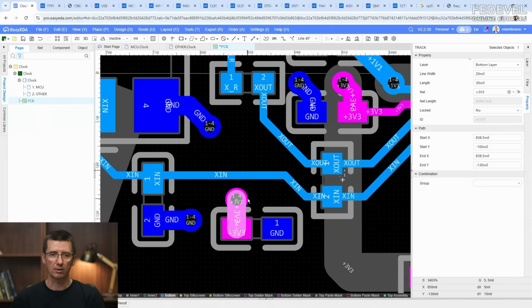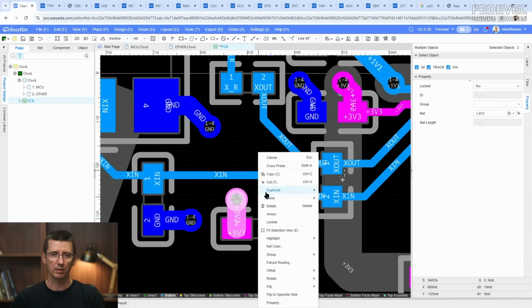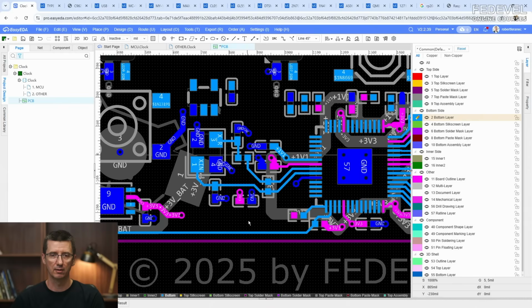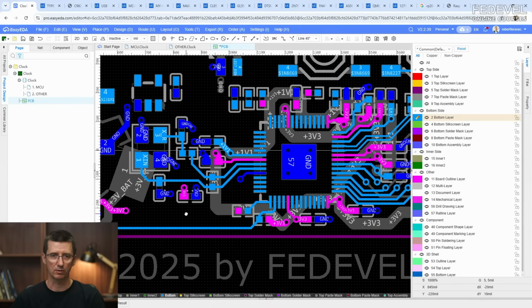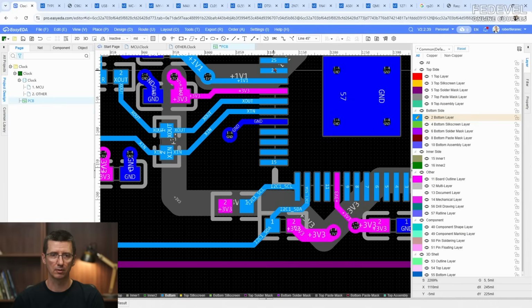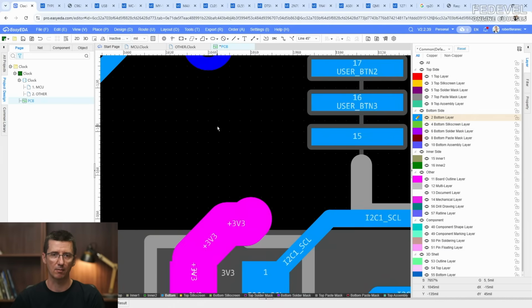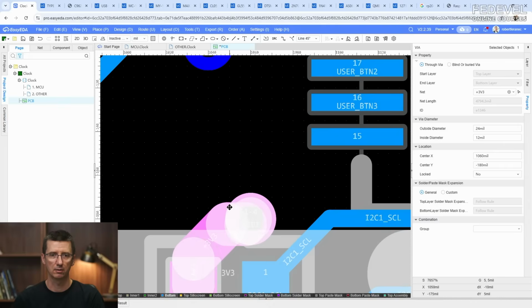The rules are actually preset from the original project, so we haven't talked about rules yet. You can just use exactly the same rules which I use for the original keyboard project, because this PCB will be manufactured by the same PCB manufacturer, JLC or JLCPCB.